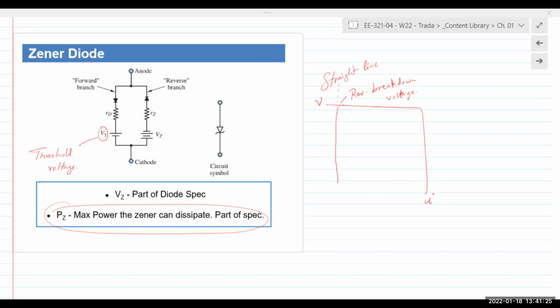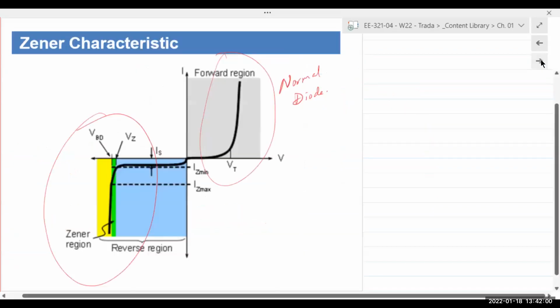Without actually being damaged. Now, most diodes typically will not be damaged when you exceed the reverse breakdown voltage. There is a reverse breakdown voltage limit known as the peak inverse voltage, PIV. So circuit designers do have to keep that in mind. But normal diodes, if you don't exceed it for longer than a few minutes, will be fine. And Zener diodes specifically will be completely fine. They're actually designed to operate in the reverse breakdown region. One note about it is that the characteristic for a Zener diode will always be in the third quadrant.